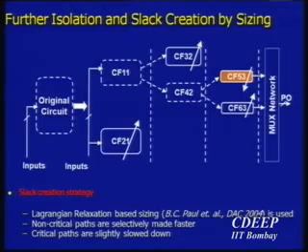In a lot of cases, certain inputs are going to be active most of the time. There are also cases when you know that an input is not going to be active most of the time. If you assume it's random, 50% and so on, then xi is equal to 1 is going to be active 50% of the time. So you can come up with the probability that x1, x2, x3 are all active at the same time, right? And if they're independent, that's going to be p of x1 times p of x2 times p of x3, right?